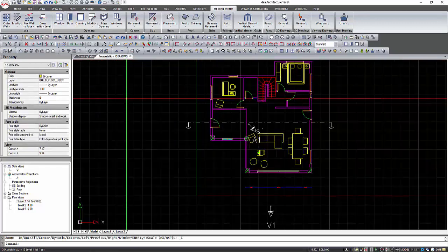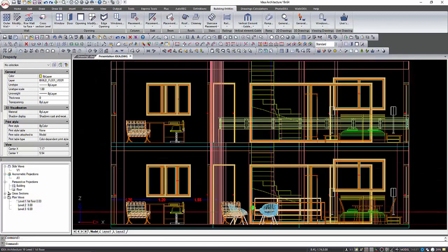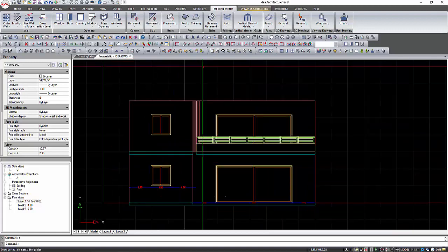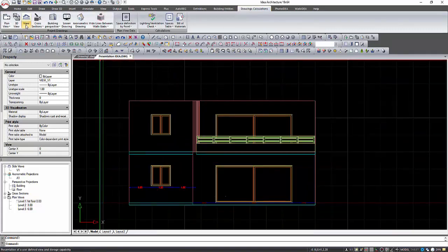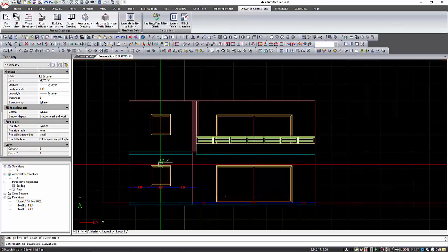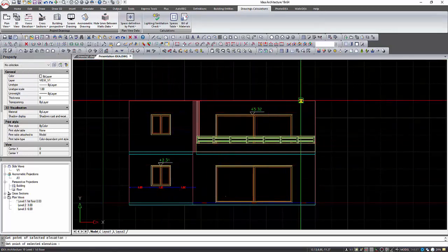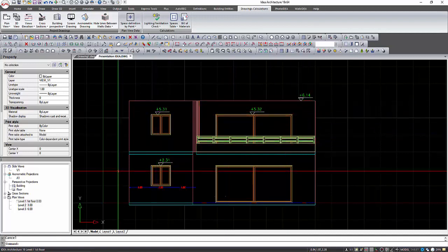We saw earlier how we create views. There are of course many more commands to see in views, sections, etc. Let's select this view and put automatically the elevations of any point on that view. With the command view elevations, we give the point that is the start of the measurement, and then, by making click to any point, the elevation is put automatically.